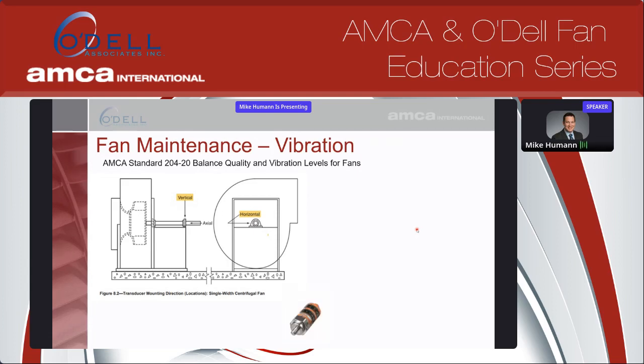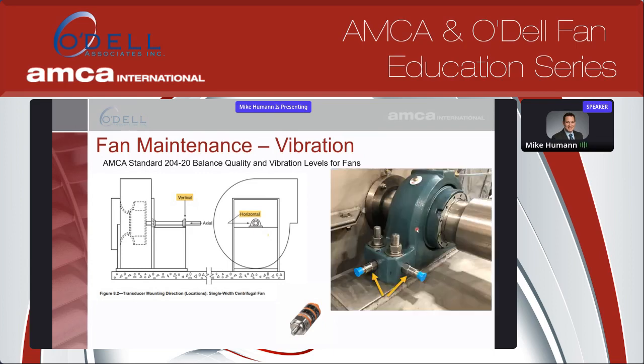Some ways to monitor vibration. You see a vibration switch down here that will attach directly to the fan bearing. You see some accelerometers here in this picture. And so this is the horizontal direction. This one's actually in the axial direction. You see it's axially parallel to the shaft. So here's a couple transducers here to help monitor vibration.